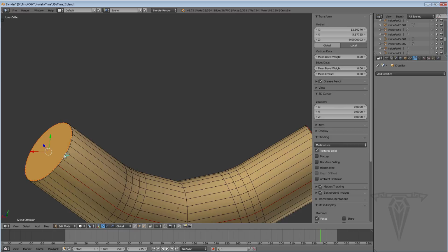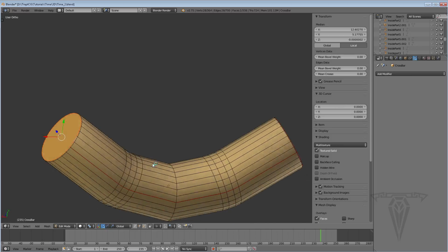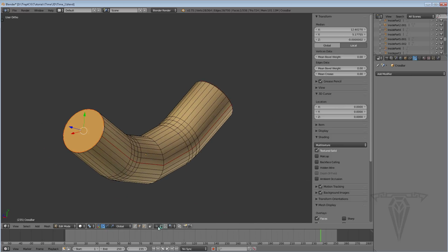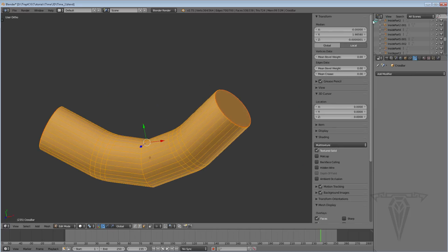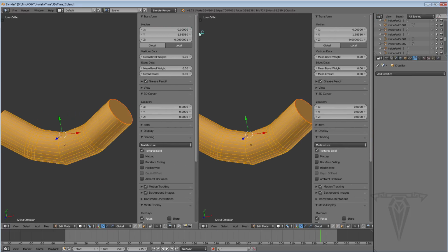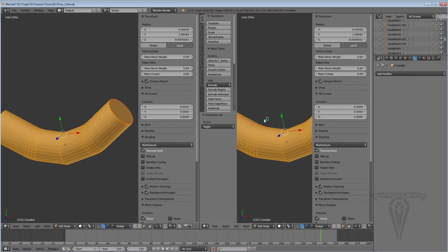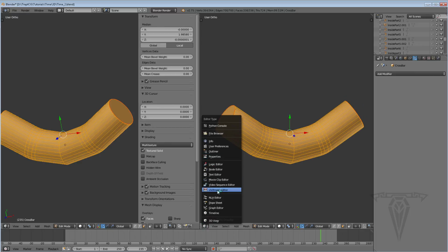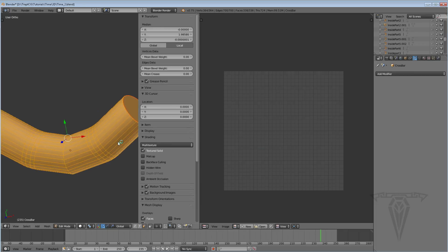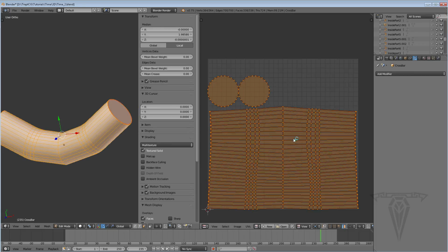Shift R, and I'm done making my seams for this object. So let's go ahead and go to polygon mode, A on the keyboard to select all. Let's open up that window again. Now this is where having two monitors really helps, so you don't have to keep opening and closing this window. I'm going to hit T and N to hide the properties, and we'll switch this view to UV editor. And I'm going to come in here, hit U, unwrap, and there we have it.